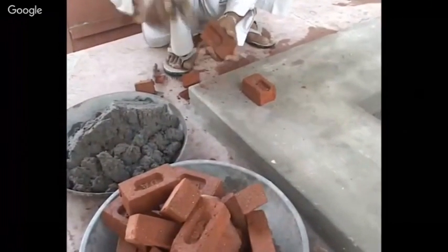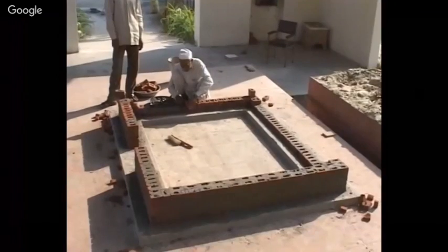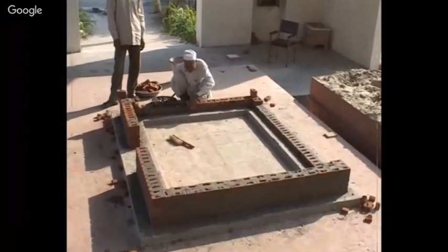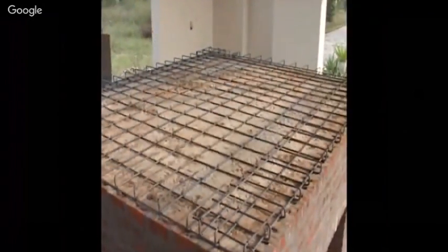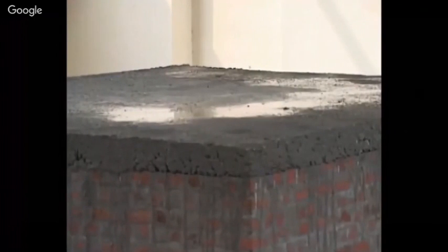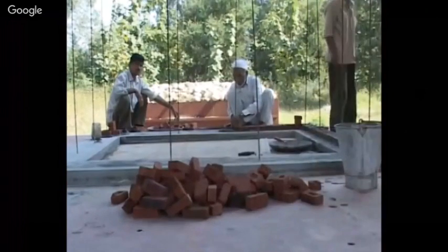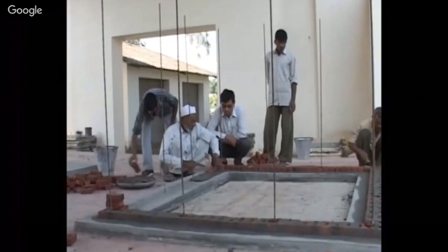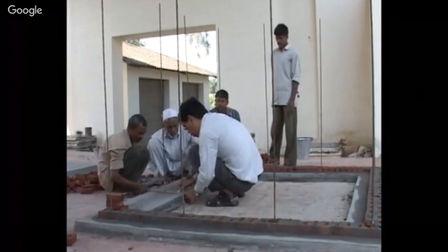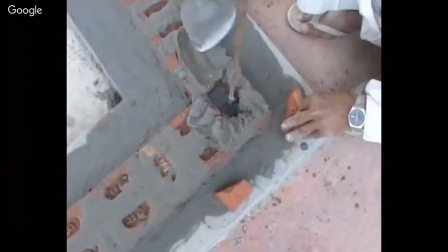Two half-scale, single-room brick masonry models are constructed simultaneously on the shock table. The first model is constructed using popular construction techniques as we have been doing for years. This model has been constructed without any earthquake-resistant features. In the second model, all seismic strengthening arrangements specified in earthquake safety codes like vertical reinforcing bars at the corners, jamb steel around the openings, and seismic band at lintel level are incorporated.